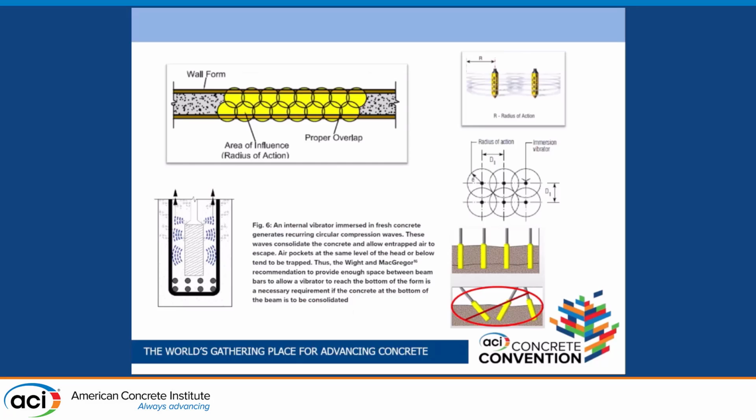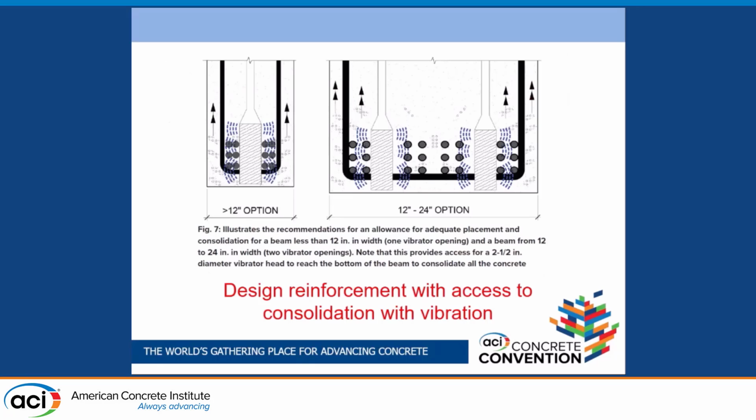Best practices of consolidation, as you see on the bottom left, this is one of the images from our paper, making sure people understand how you vibrate concrete when you have heavy congested rebar. These are best practices. You need an influence area for the vibrators to work properly. And obviously when you have a lot of rebar, how you can start spacing out that rebar congestion so you can allow those vibrators to get in.